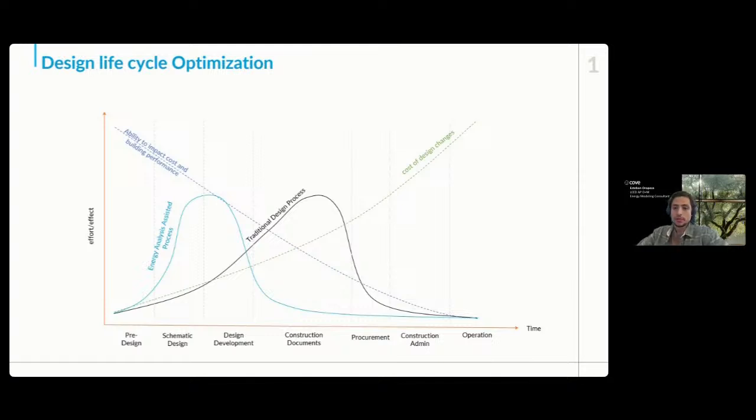And sometimes energy modeling even pays for itself pretty quick, even before construction ends or the building is operational. So it's also really about identifying unnecessary costs. An example of that could be when the HVAC design is oversized. So you're specking out probably an expensive and unnecessary system that will do the work, but won't be the most efficient option for your specific design.